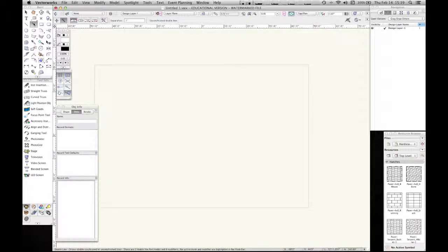So, I'm going to go up here, I'm going to click on my double line tool, and one of the very first things I'm going to do is look at this box. This box says up here in your context menu, separation. Right now it's saying 0.1 of an inch. It's saying the distance between these two lines is 0.1 of an inch. That's ridiculously small. Our pipes in the theater, they're 6 inches in width. So go ahead and type 6 inches.